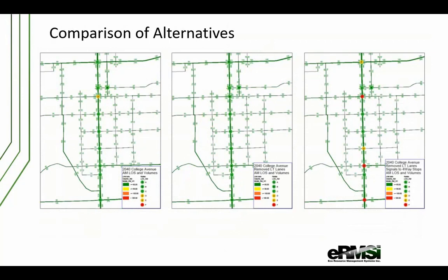And the problem really was the intersection timing, that it was state controlled, and so they had very long amber and all red times and had exclusive left phases and so forth.